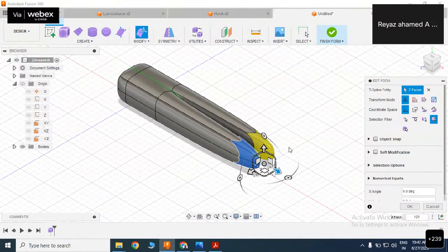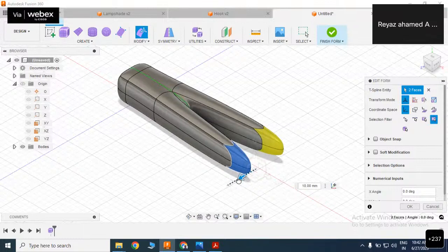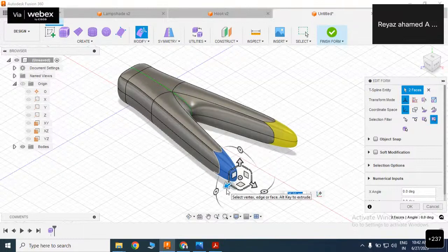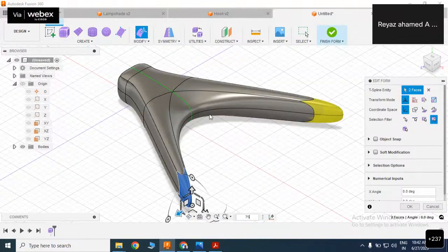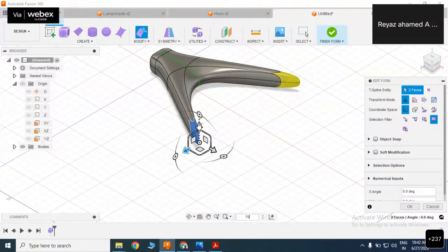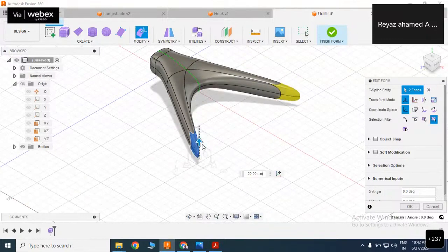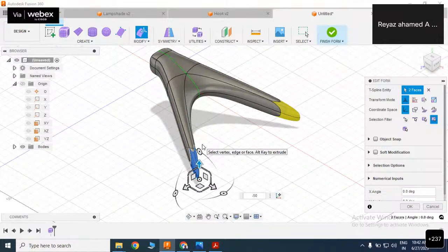And then remove the hand from the Alt key and drag this towards leftwards. Give the value as somewhat 75. And then move in the Z direction also. Give the value as -50. So all things have been done on one side actually. So just click on OK.